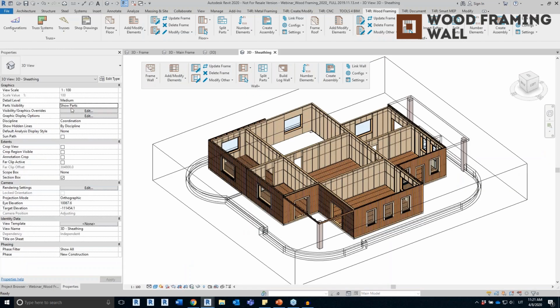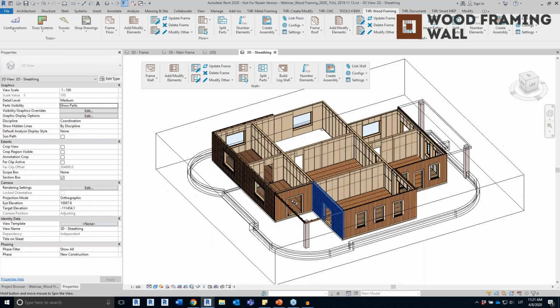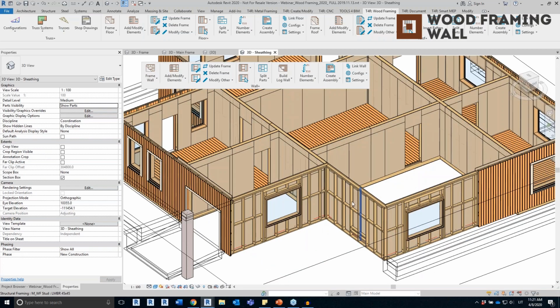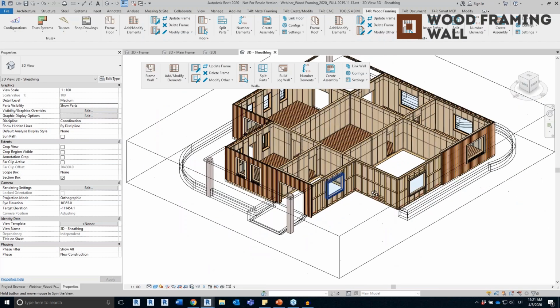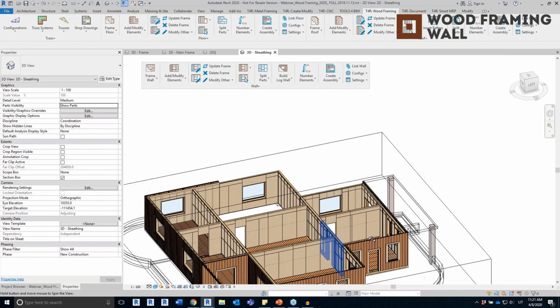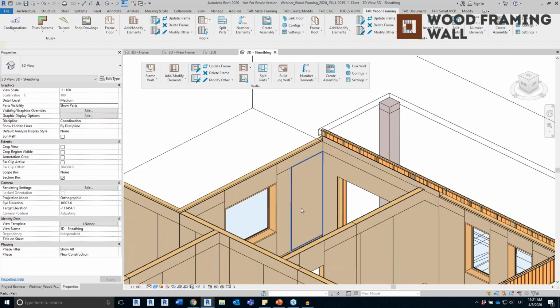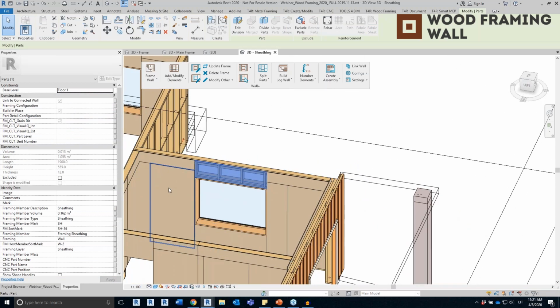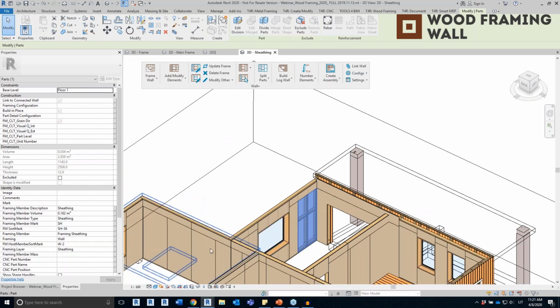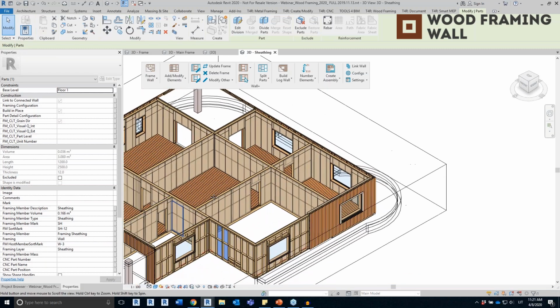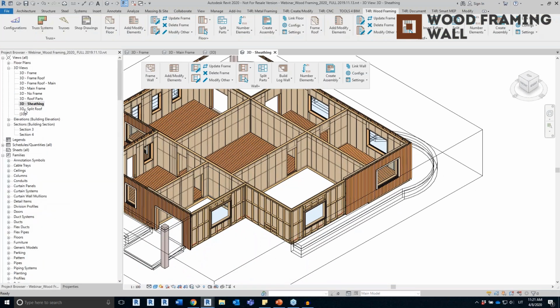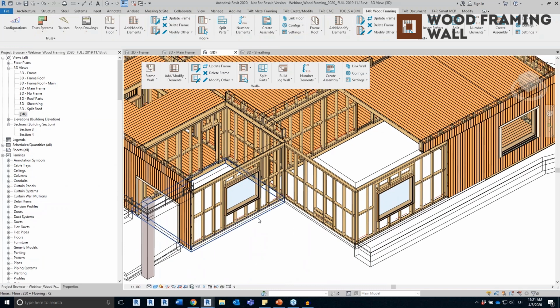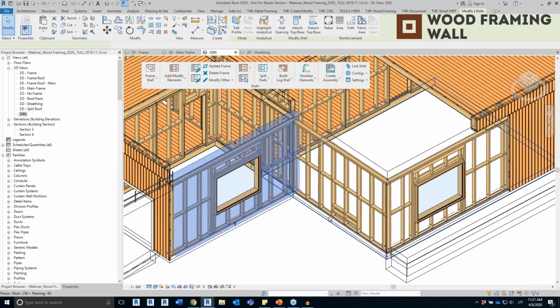So you can see that in this view, I have show parts turned on, and that is why I can see all of the parts that I have in my model, and I just split them for these 3 walls. So you can see that all sheeting parts were split according to the settings in my configuration. Again, this is just an example, so you can create your own rules for the sheetings. Okay, and now I can go back to the original view and frame all other layers.